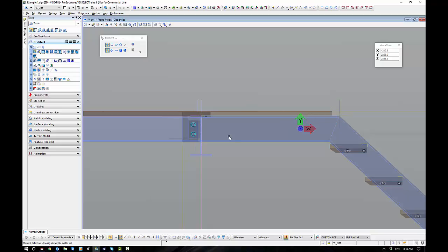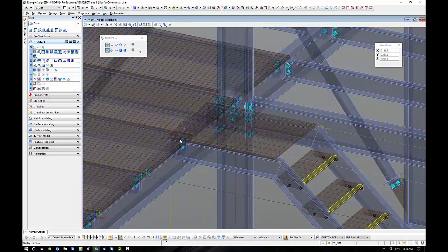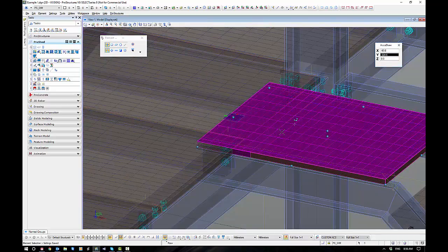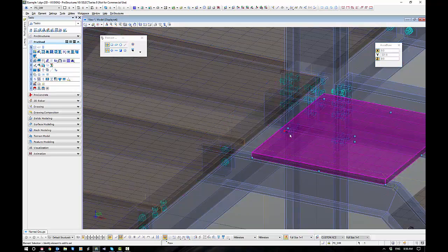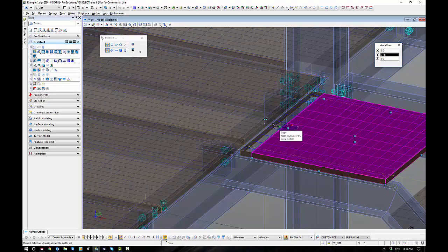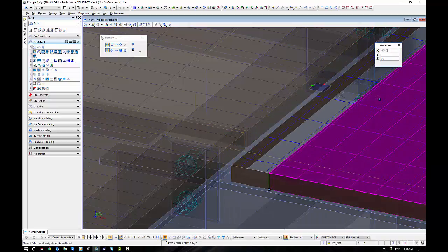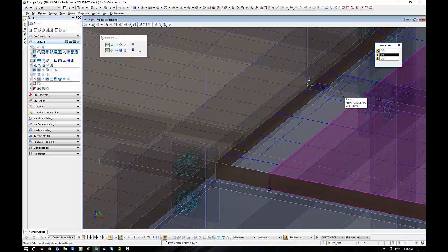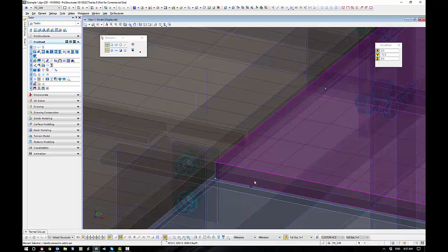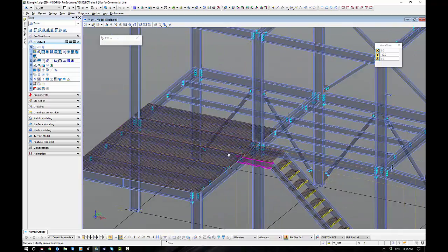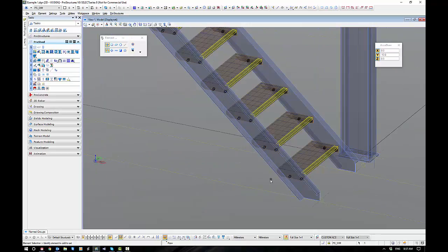And the last thing we've got to do is shorten this up and connect this up. So we'll do this in the aeroplane mode. We'll kick off by tidying this bit of grading up that's overlapping. So I'm going to pull it back from the center node so it pulls back nice and square, and then we're going to drag it back. We're going to set a tentative snap to here that becomes my origin, O for origin, and then pull it back 10 millimeters. Okay, so there's a 10 millimeter gap between all the grading.